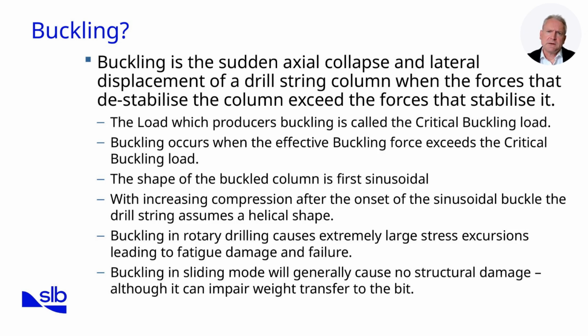Initially, this deformation appears as a sinusoidal wave, where the pipe gently oscillates against the borehole wall. As the load increases further, sinusoidal buckling transitions into helical buckling, in which the pipe coils around the borehole wall. This helical shape greatly increases side forces, contact stresses, and friction. The largest stresses occur when buckling in rotary drilling. When sliding, there is usually no structural damage, but it does impair weight transfer. In summary, buckling is a critical design consideration because it reduces efficiency, damages equipment, and increases operational risk.